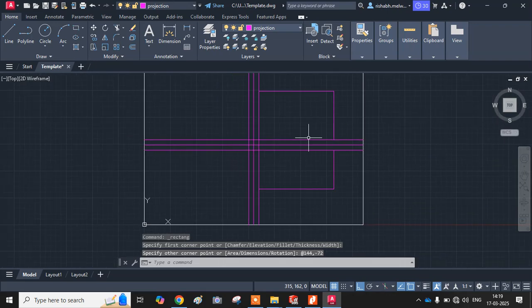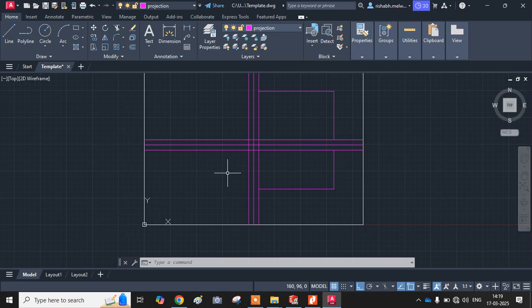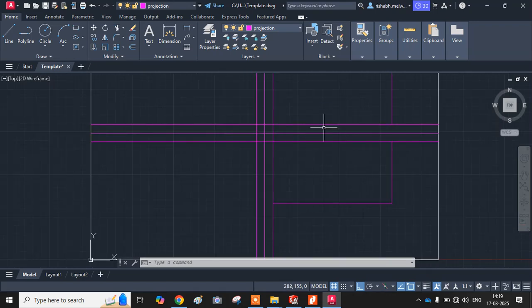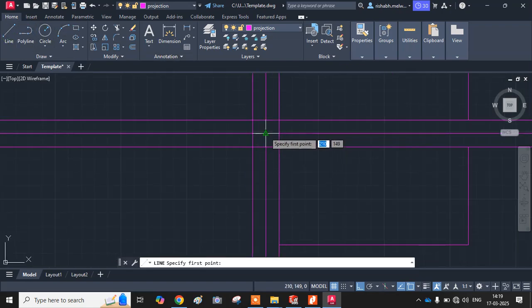Now side view, how do we have to draw? Simply I will draw a 45-degree line over here na. So in order to draw that 45-degree line, either you can calculate this angle, this will be from the positive x-axis: 90, 180, 180 plus 45, that means 225. Or the second method, what I have explained, that second method. See, what is the second method? Without any angles we can draw.